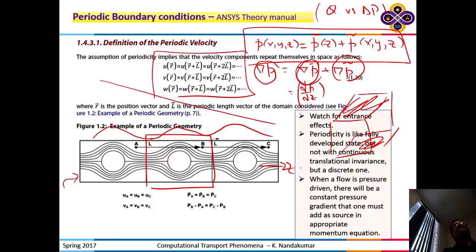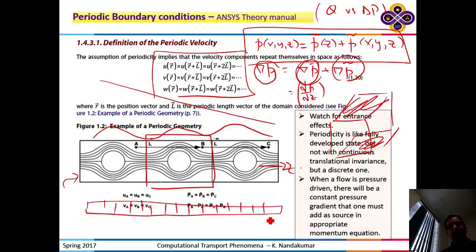So periodicity in that sense is an idealization. So you will never be able to use it to construct real systems. But depending on the length to diameter ratio, if you have a long channel like that and you find the periodicities of this order, the solution that you get by taking one cell will give you a reasonably good approximation of what the delta P is over the entire one by adding it up, except the errors introduced by the entrance length effect here and the exit length.